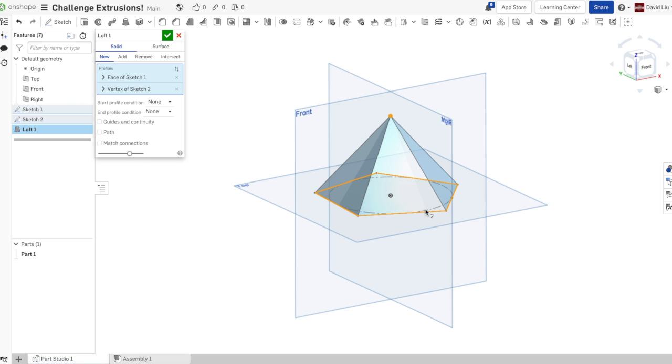This is very different from extrudes. When you're doing an extrusion, you have a polygon, and then you press extrude, you press one face, and then you say how much do you want to extrude this by? 1 inch, 2 inches, whatever. But in this one, you can use two different sketches on two different planes to create something like this. So that is not even as interesting as it gets. Basically, I just showed you how to pull a surface or a polygon to a point. Now I'm going to show you how to pull a polygon to another polygon of different sizes.